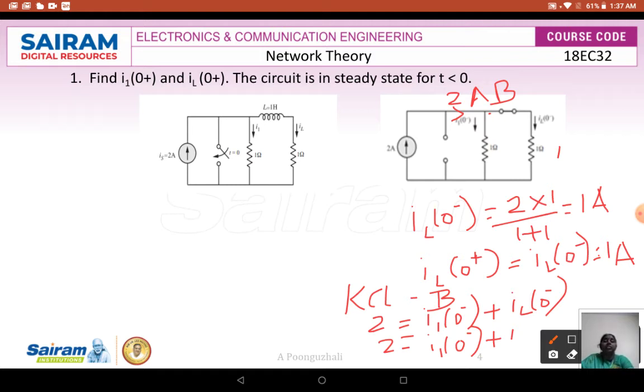This I1 of 0 minus is when the switch is in the open state. When the switch is in the closed state, we will see it now. If the switch is closed like this, your 2 amps current will flow like this and no current will flow through this part of the circuit. That means your I1 of 0 plus is going to be 0. So we can say that your current has changed from 1 amperes to 0 amperes.